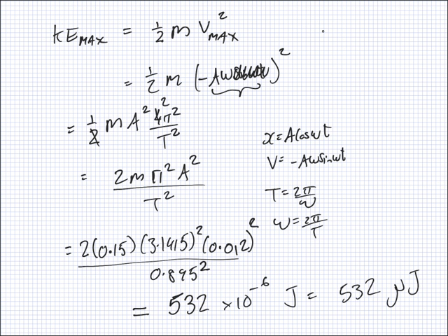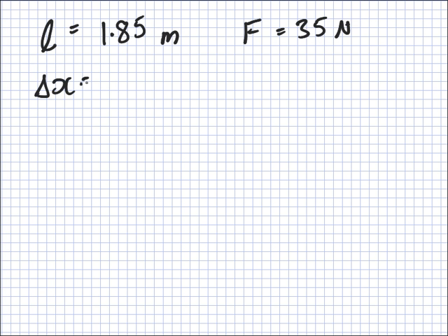Okay, the next one I think was okay. It was Young's modulus with stress and strain. The question was, you have a wire and its length is 1.85 meters, and there's a force applied to the wire of 35 newtons, and the wire extends a distance of 0.78 millimeters. The first question is, what's the strain?